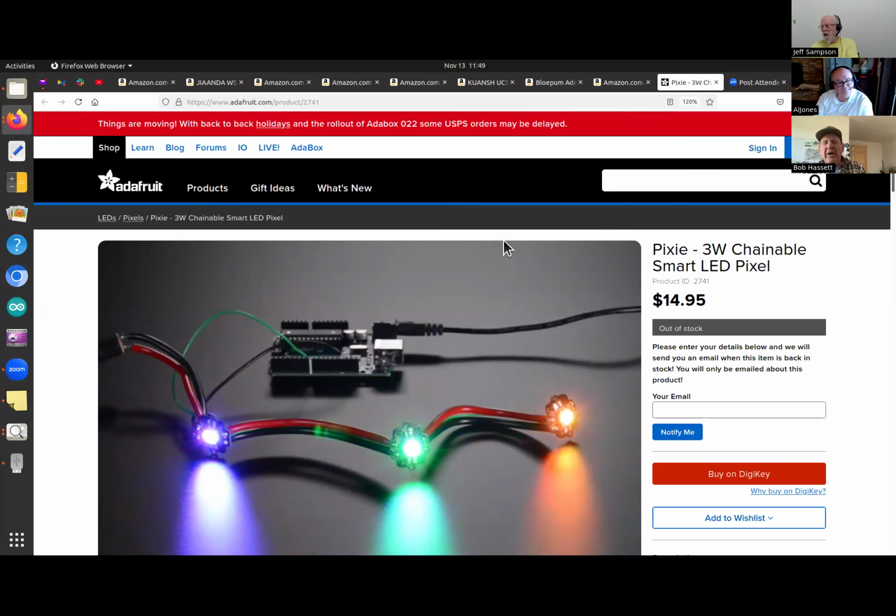Here's one that, it turns out, Adafruit makes: a high power LED pixel. And these are addressable. But if you look at this hard enough, they don't seem to be compatible with a NeoPixel, the WS2811 format. I think each one of these modules has a microcontroller on it, and I think they just have a UART interface. So you basically do the same thing. You say, here's my 24-bit color, but you send it out as UART messages.